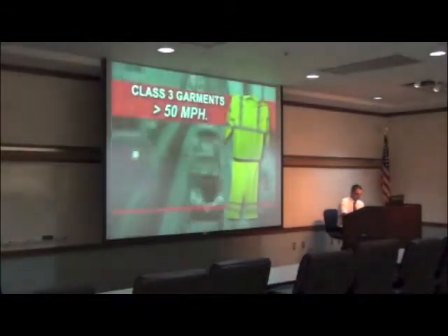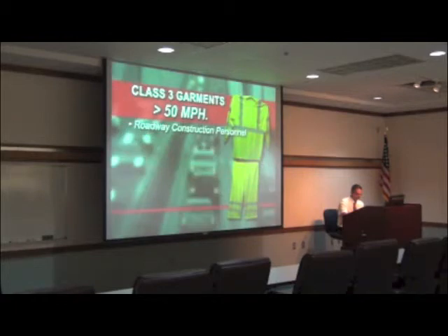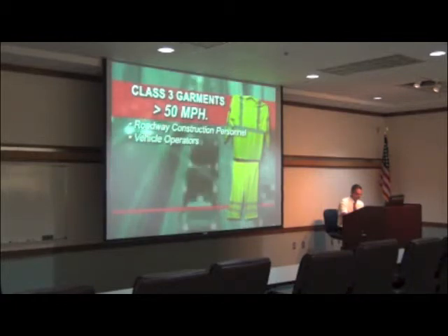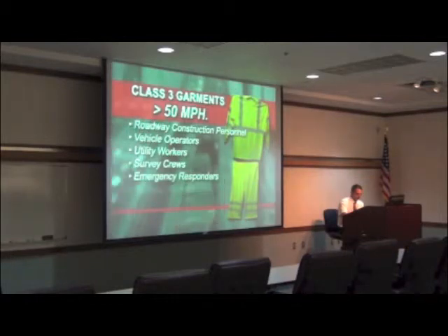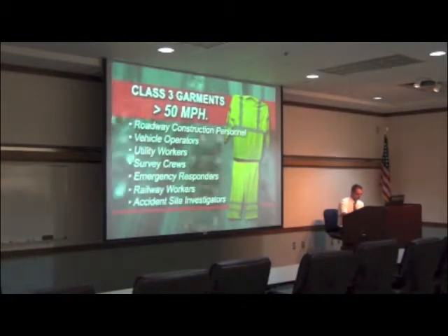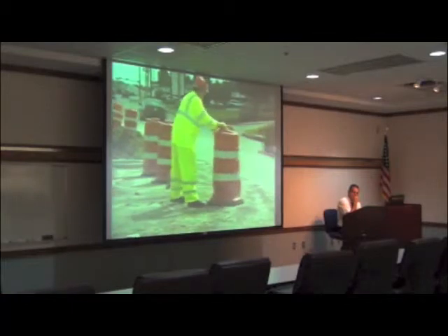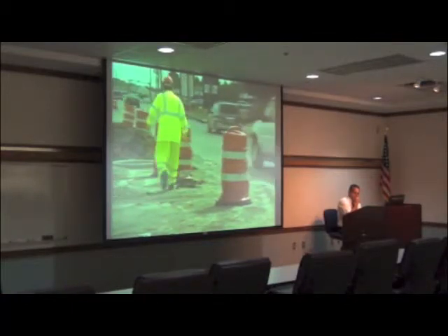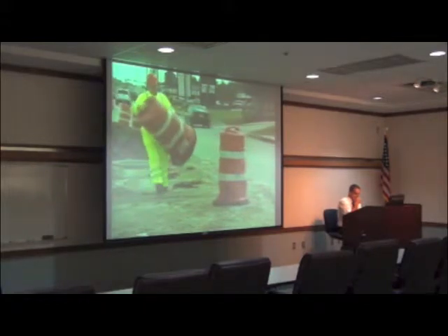Workers who generally wear Class 3 garments include all roadway construction personnel, vehicle operators, utility workers, survey crews, emergency responders, railway workers, and accident site investigators. Employees who perform maintenance and protection of traffic operations in situations where their attention may be diverted from traffic are particularly at risk and should always wear Class 3 garments.